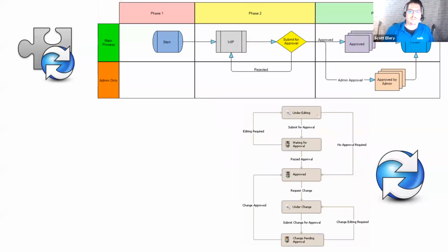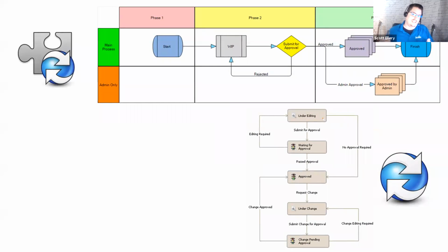With Manage, it's a little different, where the process looks similar, because it's laid out with states and transitions, just like you would have in PDM, but the entire company or the entire user base, or whoever needs to be able to see where we are in a process, has access to that. We can also start a process without any file at all. If we just want, in this case, an engineering change, we just say, I want to start one. I don't need to have a source document to do that.